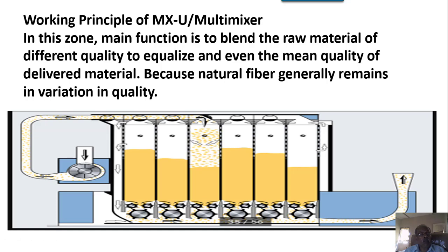Here we have the input of the material from the previous department, that is if you have a pre-opener etc., then blendomat pre-opener, and in between if you install a foreign fiber detection system, from there now the material in the reduced tuft form will arrive here in this chamber.